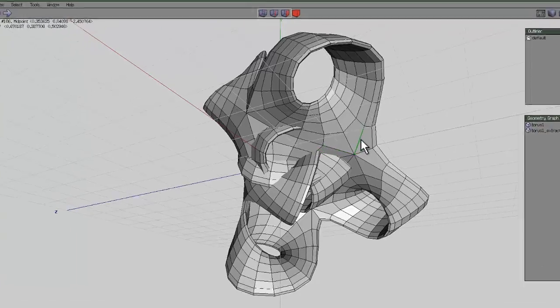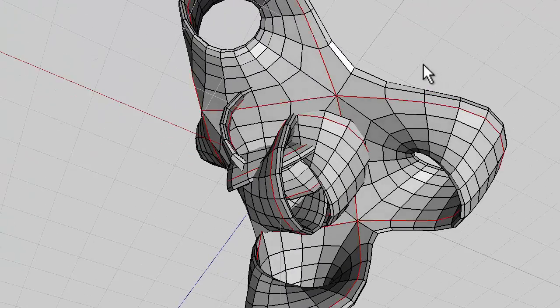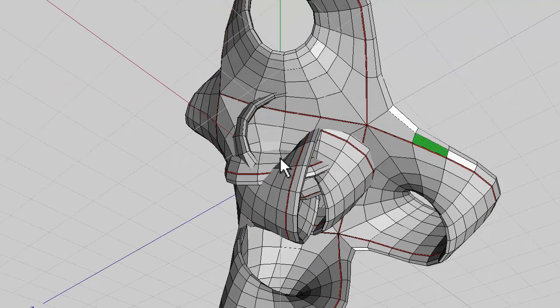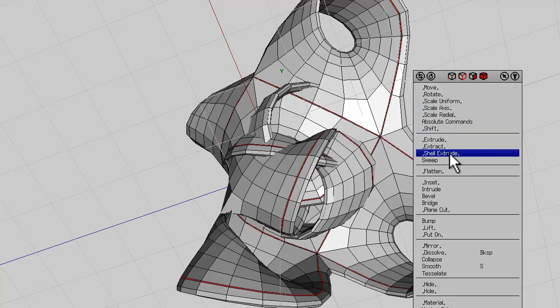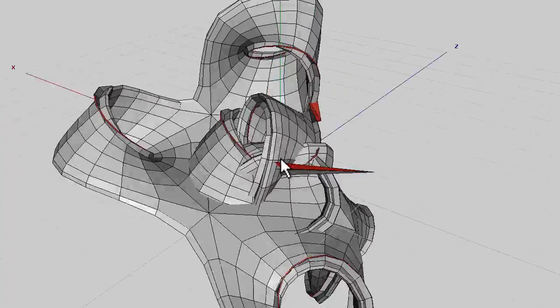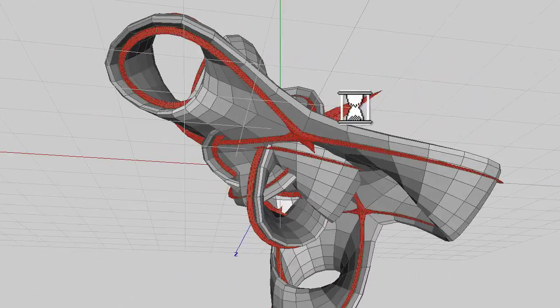For visibility, go to the other side and select the corresponding lines there, and I'm going to loop those round, and I'm going to bevel those just to show you there's another option there, and then I could shell extrude that to get a different shape coming out in the other direction. You see this spike that's formed? That's obviously bad geometry. Now if I smooth, that might disappear.